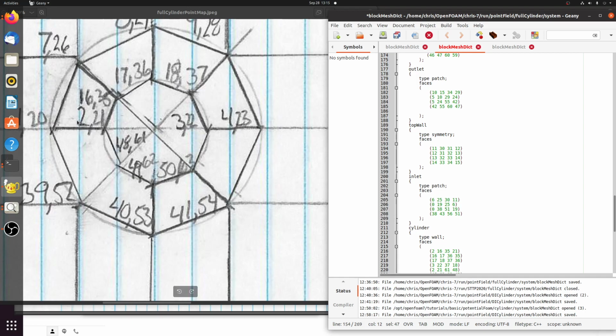The left is the back plane, and the right is the front plane, after we grow Z out. If we're going from inside and going out, we'd be going this direction and we hit it, so we want to go clockwise with the four points before we hit it. 2 is in the back, 21 is in the front. I like starting out with the smaller numbers. It makes it a little more challenging sometimes, but it keeps me organized.